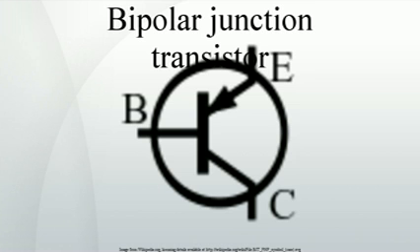Avalanche breakdown region. Although these regions are well defined for sufficiently large applied voltage, they overlap somewhat for small biases, less than a few hundred millivolts. For example, in the typical grounded emitter configuration of an NPN BJT used as a pull-down switch in digital logic, the off state never involves a reverse biased junction because the base voltage never goes below ground. Nevertheless, the forward bias is close enough to zero that essentially no current flows, so this end of the forward active region can be regarded as the cutoff region.